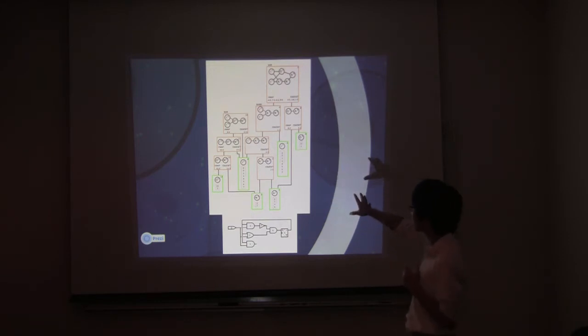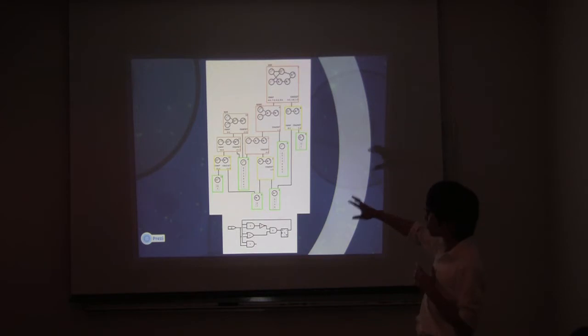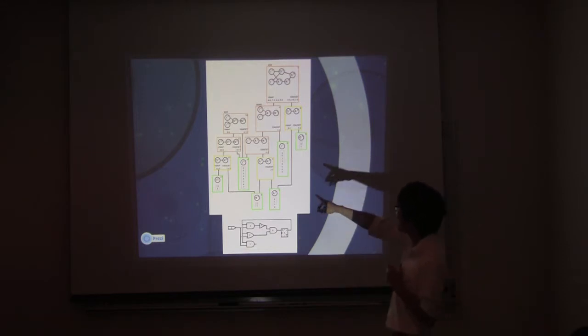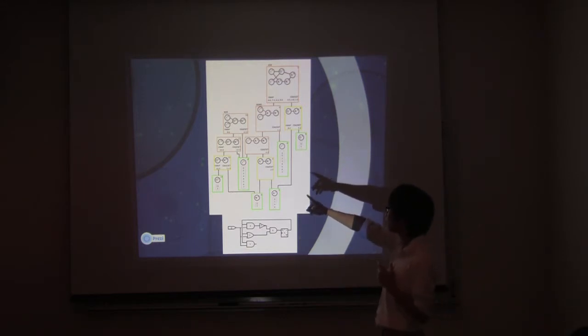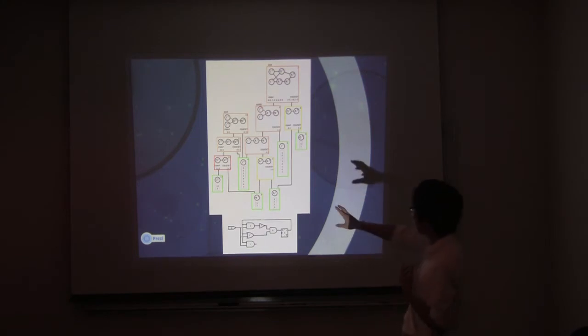Once all the mappings of the single vertices have been made, the next step is to try and combine, pretty much build a circuit from the bottom up. So the next step is to look at the nodes whose both child nodes are marked alive. So the nodes marked in yellow have the 2 child nodes marked alive. As for the first one, since it's an OR gate connected to an inverter, there is no such instance located here. Because there is no mapping to be made, the node is marked dead.